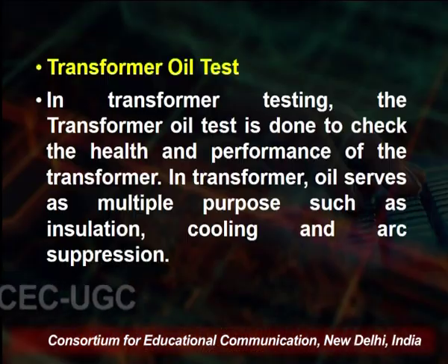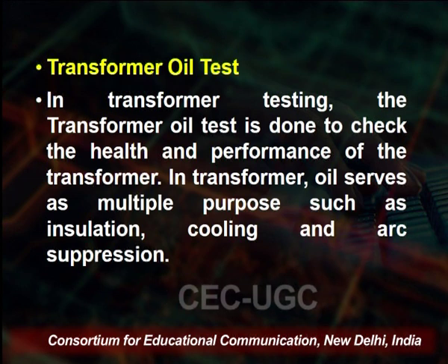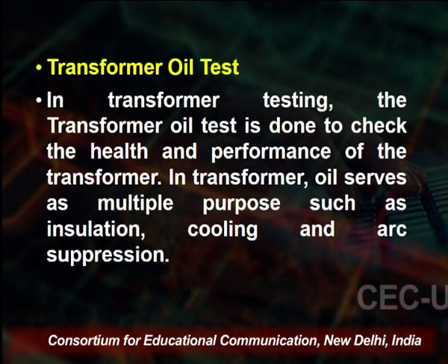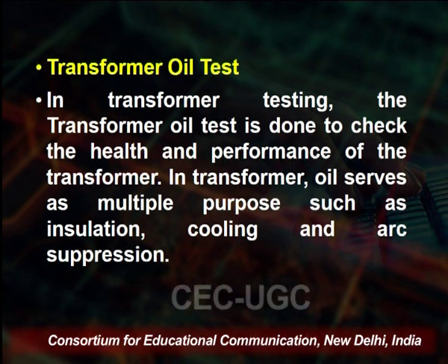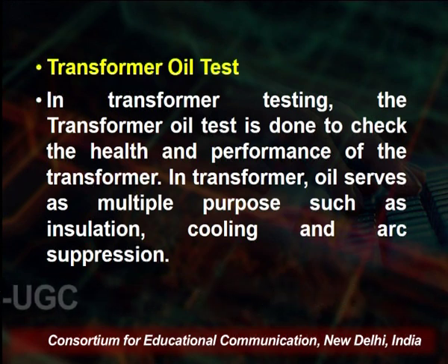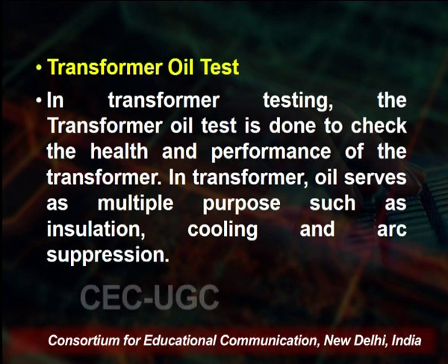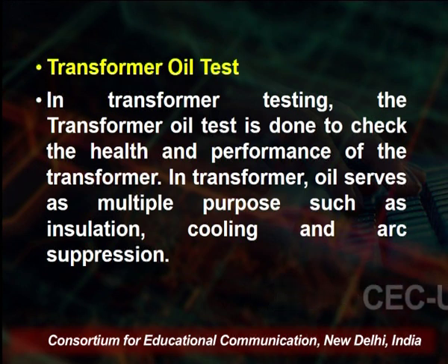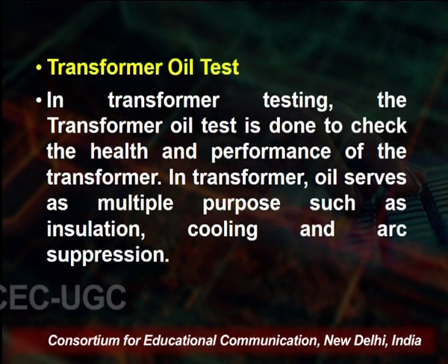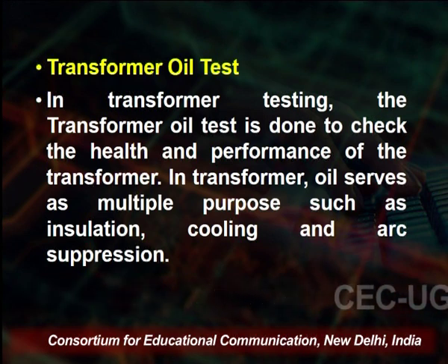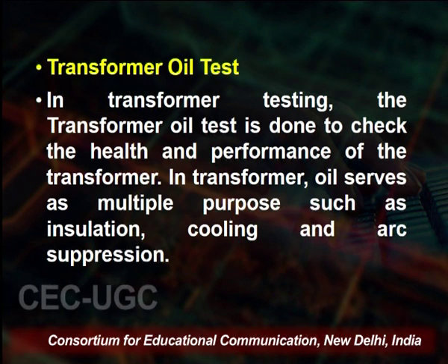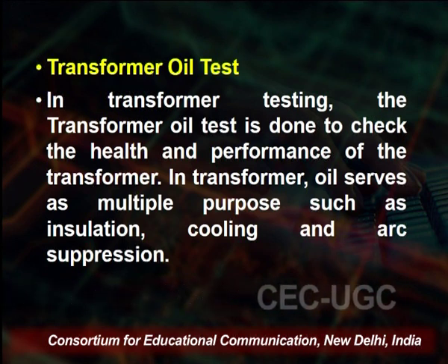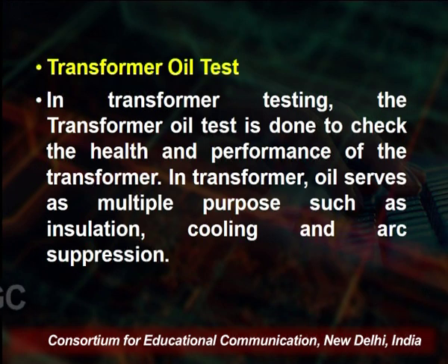Another test in transformer testing is the transformer oil test. The transformer oil test is done to check the health and performance of the transformer. In a transformer, oil serves multiple purposes: it is used as insulation, for cooling, and for arc suppression. That we can measure through transformer oil testing.